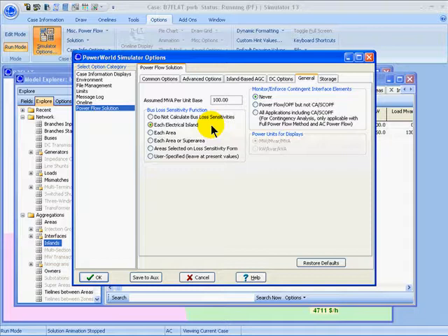Each electrical island will basically calculate the bus loss sensitivity for an injection at each bus, and it will determine how the losses change within the electric island that that bus belongs to. The injection is assumed to be taken out at the island slack bus.